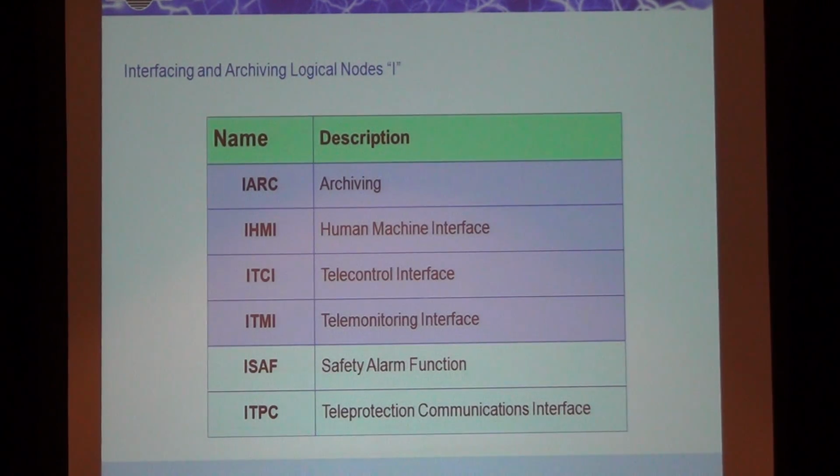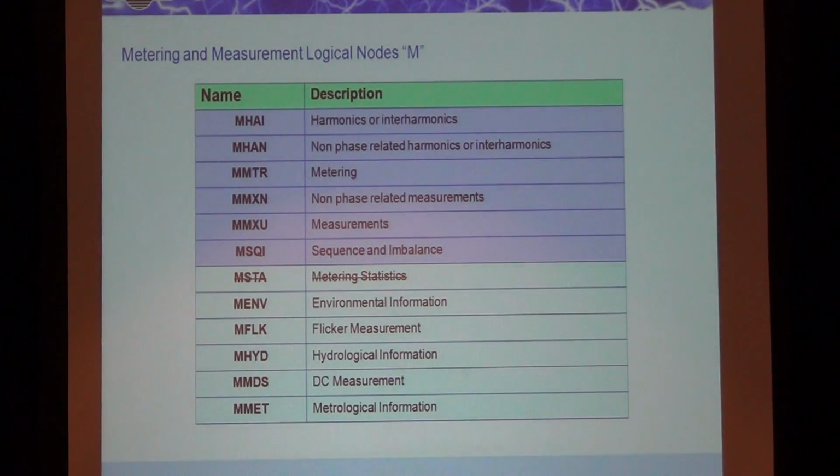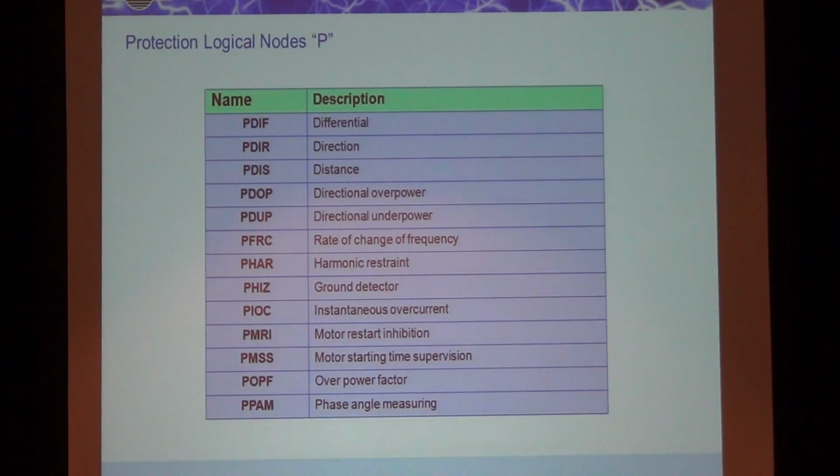Interfacing and archiving, beginning with an I. You've got mechanical and non-electrical type things like filters and pumps and tanks. Metering and measurement logical nodes, harmonics, measurements. You've got sequence and balance, statistics, hydrological information, DC, etc. Many protection functions. Instantaneous over current, differential direction.